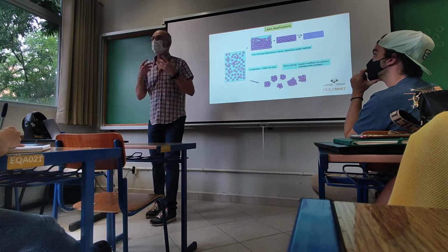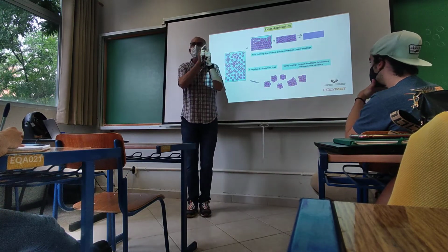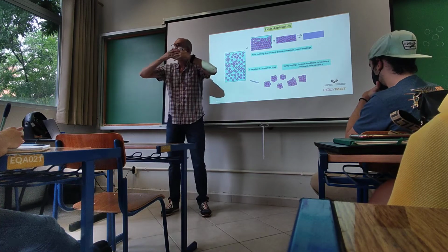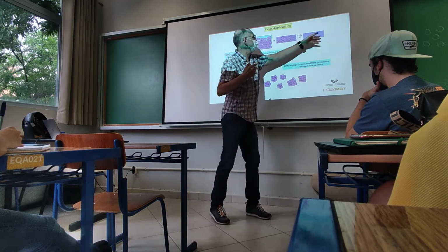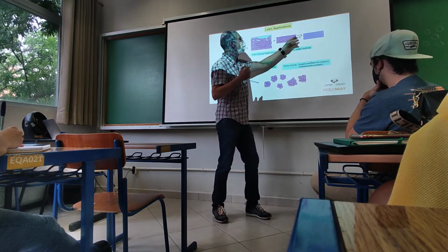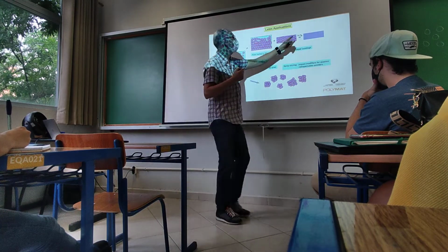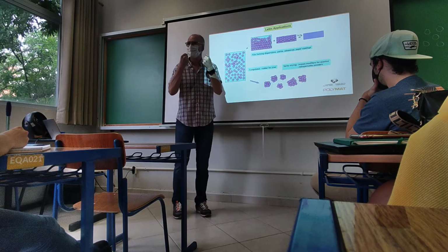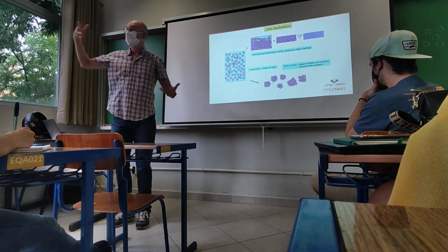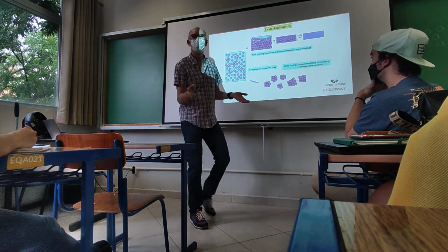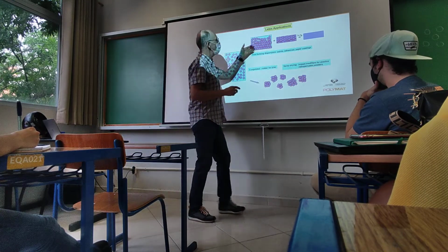Polymers in solution, when you cast a polymer in solution, you don't have boundaries. So the polymer in solution interpenetrates and the films are normally better than in emulsion polymerization. So there is plenty of research done on this, no? Because if you want to produce a film which is strong mechanically, you normally need to use polymers with high TGs. But if you have high TGs, you cannot form film at room temperature, so you cannot paint. In Brazil, probably you can. In other countries, it will be more difficult. Okay? So this is one of the ways to use it.